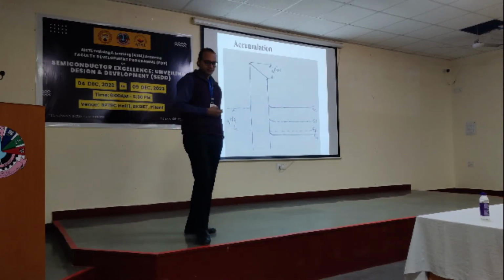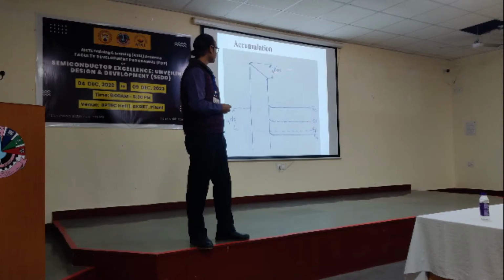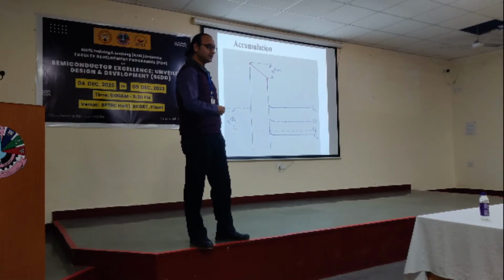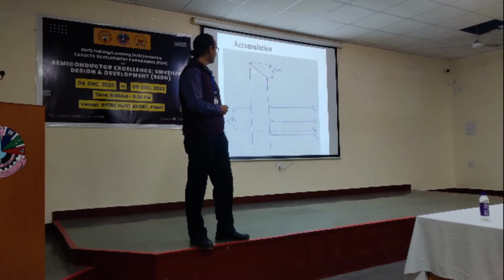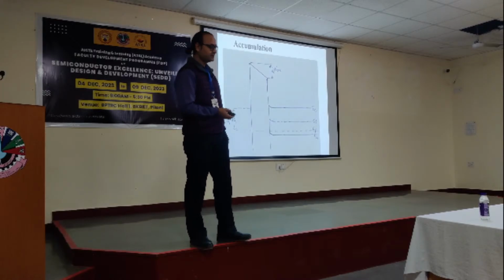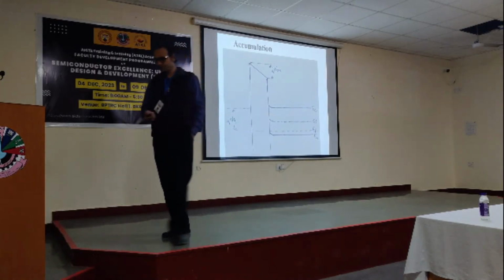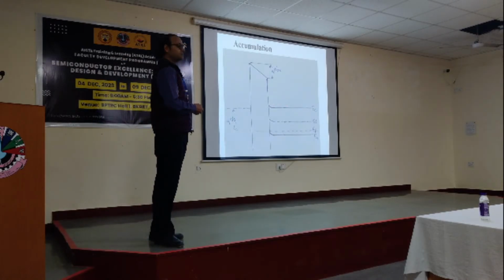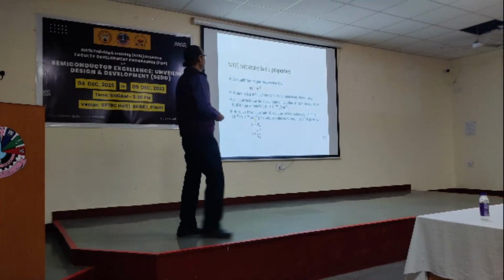We call this band bending, and whatever the amount of bending, everything will bend except the Fermi level. The bands will bend accordingly in the oxide also. That net bending across the oxide we call the voltage drop across the oxide, in terms of energy multiplied by Q. That much energy is absorbed by the oxide. So that is a very basic concept.